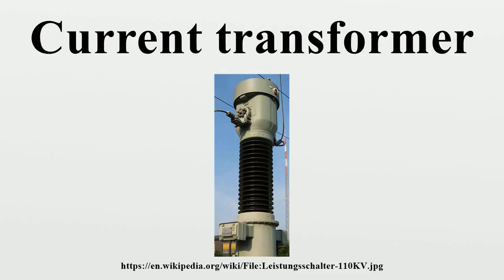In a switchyard, live tank current transformers have a substantial part of their enclosure energized at the line voltage and must be mounted on insulators. Dead tank current transformers isolate the measured circuit from the enclosure.